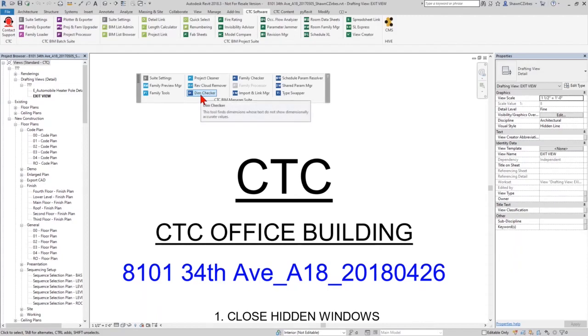Okay, another great project cleanup tool is DIM Checker. This tool allows you the ability to discover in the project where people are in dirty ways overriding the values of dimensions. I'll show an example of this a little later on. This is one, I hate to call you out, architects, but the MEP and structural teams really depend upon your dimensions, and I've seen some architects in some places do some pretty dirty overrides, and this tool helps you discover those as an MEP and structural engineer